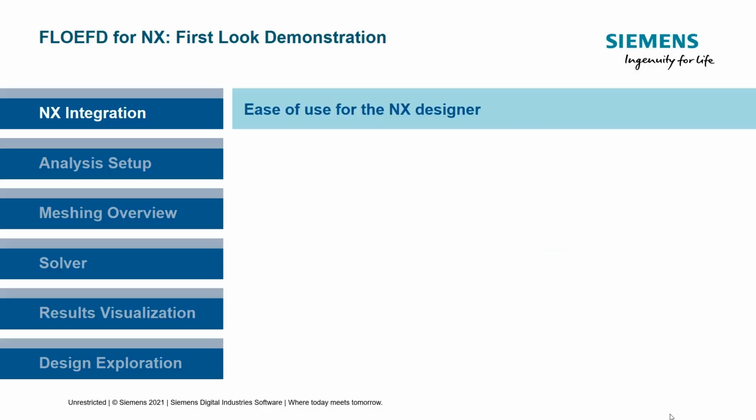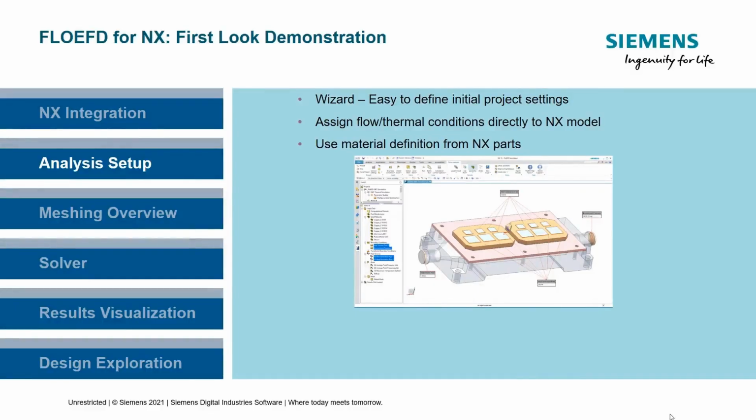What we just saw was the NX embedded nature of the software and how designers can leverage pre-existing NX models to perform a CFD analysis. The familiarity of the NX interface and FloEFD being a logical extension makes the tool easy to use for the NX designer. The FloEFD project is created using a wizard-driven process. Flow and thermal boundary conditions are applied directly onto the NX parts. If materials have been applied in NX, these can be imported directly into the FloEFD engineering database.